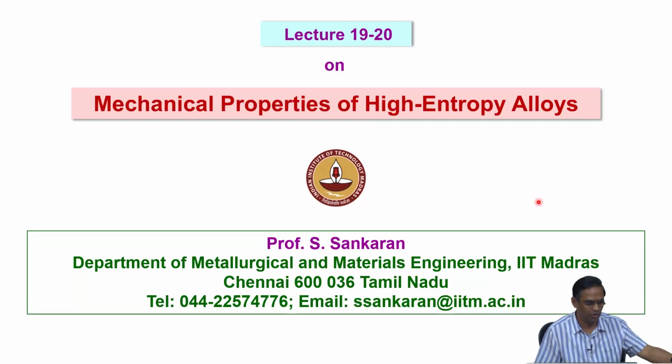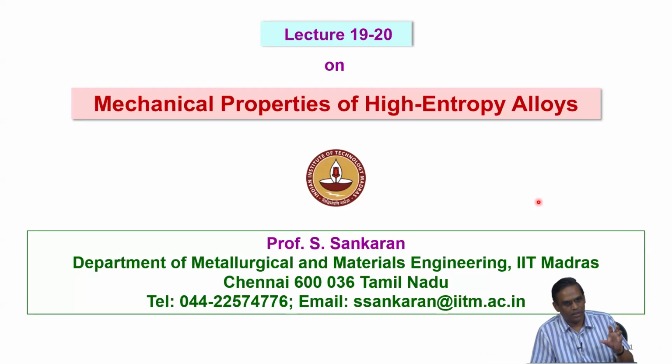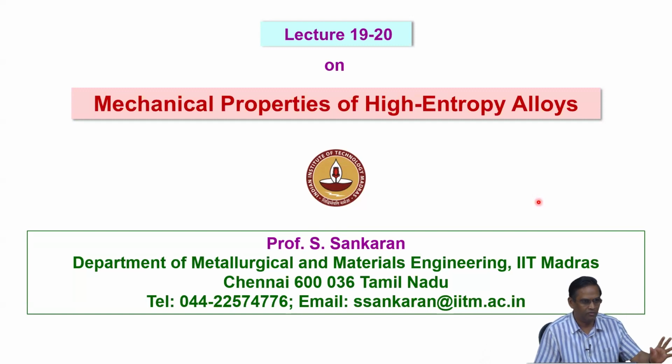than in the pure lattice. On the other hand, if you look at any of these mechanisms, because you already have a distorted lattice which has additional energy compared to a normal lattice, the dislocation core energy is also slightly different from the conventional pure metal or any alloy, because it is a multi-principal component alloy which is completely distorted.